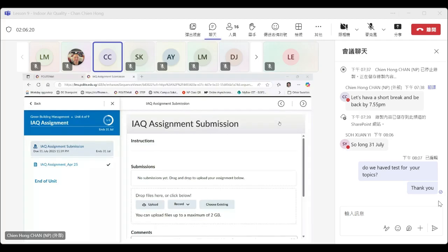So in the building, you can even comment how's the ventilation design. Is it adequate for that kind of situation? Right? Because this kind of industrial buildings likely is non-aircon in many of the space. So they depend on ventilation, whether mechanical ventilation or natural ventilation.